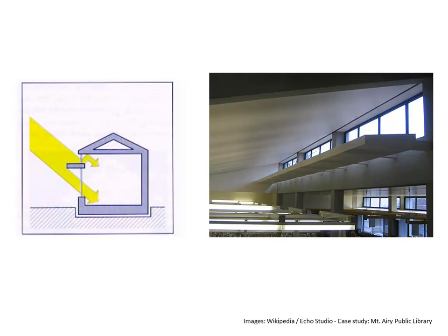This is one I'm not going to specifically cover, but it is a daylighting tool. A light shelf is basically what you see here, this kind of rectangular piece. What it does is it prevents direct light from getting into this space, but it increases the overall ambient light of the space by bouncing the light off of the ceiling. So it serves a dual function. These are not parametric. You're not going to see ones that shoot in and out. I don't know, maybe we could design one that does, but there's no reason to do that.